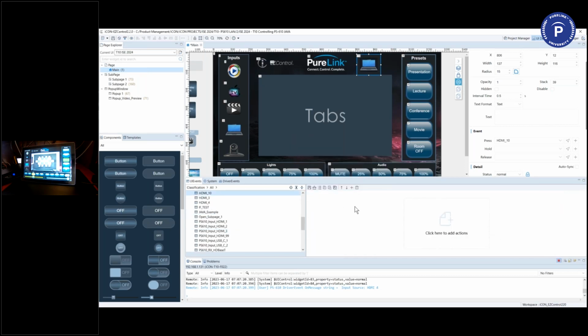Here it is. Now, when I want to add some code, I can click right here and start a new line, and it limits me to legal things that I can do. I want to change the input of my switch, so I want to send a command through the switch driver. I'm using my mouse, by the way. I just clicked on call driver, and then it asks me which driver I want to use.